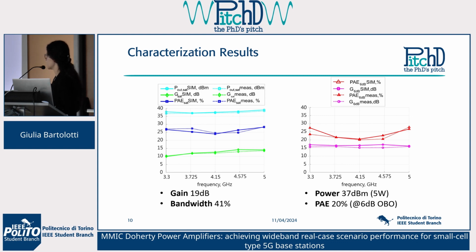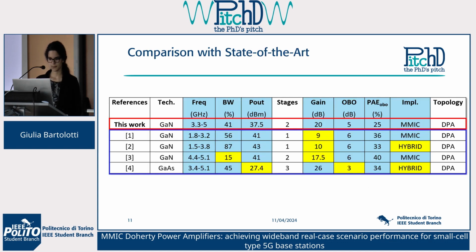To resume, the small signal gain was higher than 19 dB. We achieved this performance over the whole 41% bandwidth, and the power was the targeted one of 5 watts, and the PAE was higher than 20% both at saturation and in back-off.